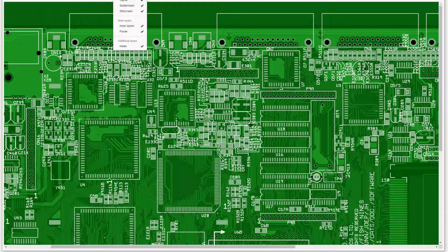So for me, spending time looking at the layout of the board, where the chips are, where the major components are, is really useful because I get an idea where on the board I want to go. We finally get up here to these two DC blocking caps we talked about, where the amplified audio, or the buffered audio I call it, comes in and then comes around to the connectors for the outputs. These two caps live here and here.